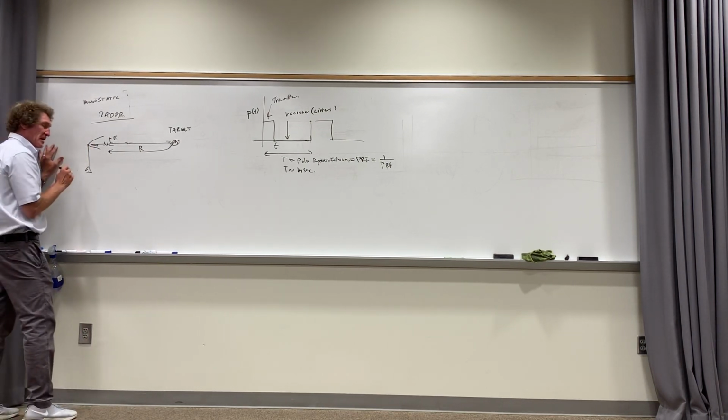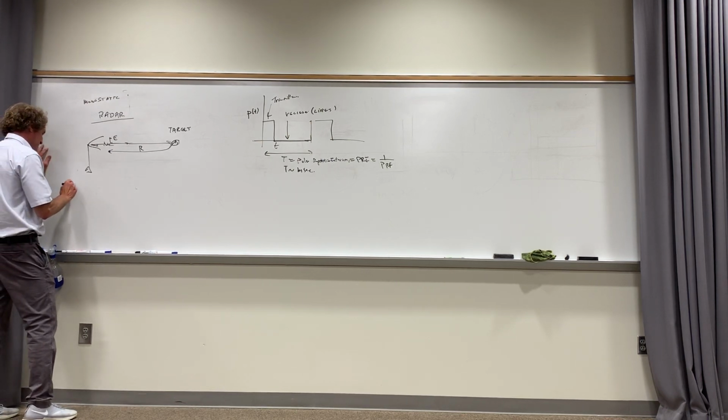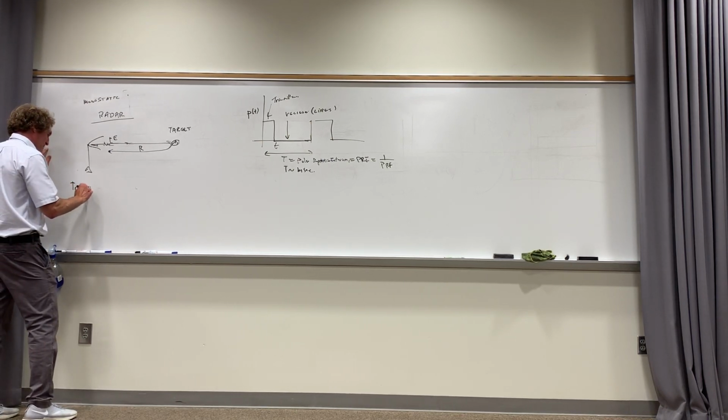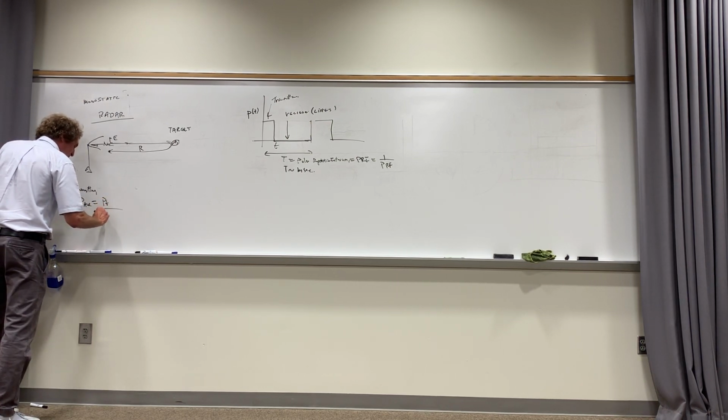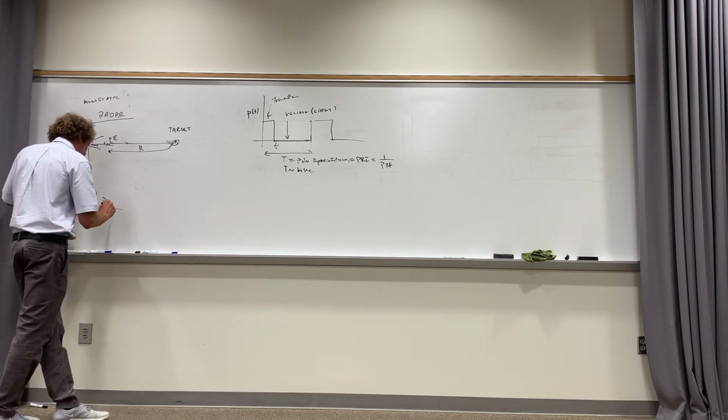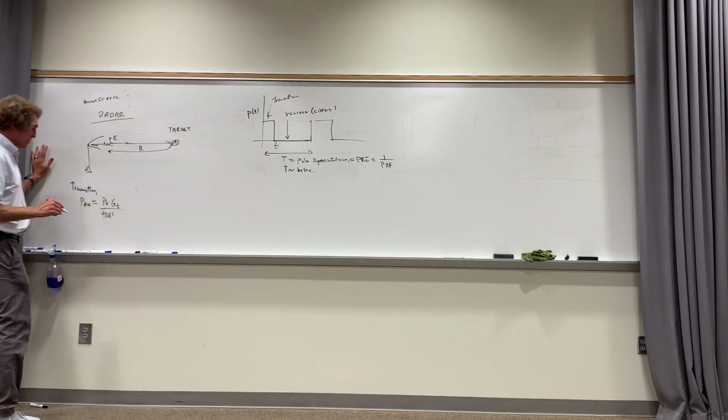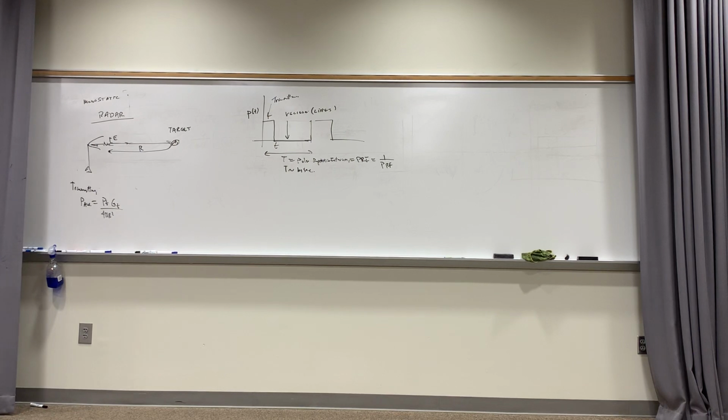If I have just an antenna and I'm transmitting here, I have an average power density at any given range of the total transmitted power over 4 pi R squared times the actual gain of the transmitter. Do you agree with me? That's the power density that would be in the waveform of a transmitted wave. And you have PT as your transmitted power, and the gain is G. Agreed, class? Now it goes out and it strikes this target.